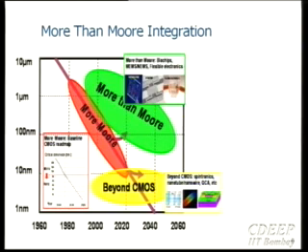But interestingly enough, the one shown in green is the more than Moore domain, meaning that yes, it's possible to have devices which are probably larger than the devices of today, like thin film technology or MEMS, or for that matter, other kinds of biochips. Maybe one can think of having chemical sensors or biosensors on chip. If I can add some of those electronics along with CMOS, then I can get a large improvement in functionality, and of course, lower cost. Some of those technologies in the more than Moore domain are going to be low cost. Sometimes you're not going to be able to implement them with a standard silicon CMOS process. So that turns out to be important as devices which can be integrated along with standard CMOS technology to get more functionality that you wouldn't be able to get with just silicon. So that's one domain that is turning out to be quite interesting.